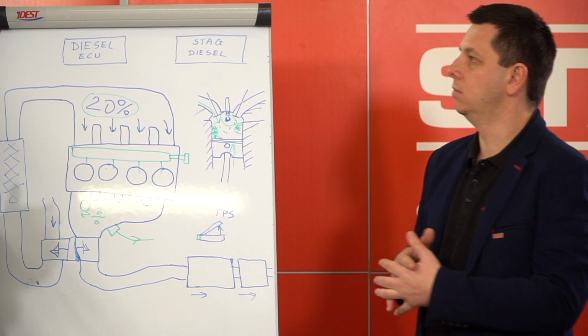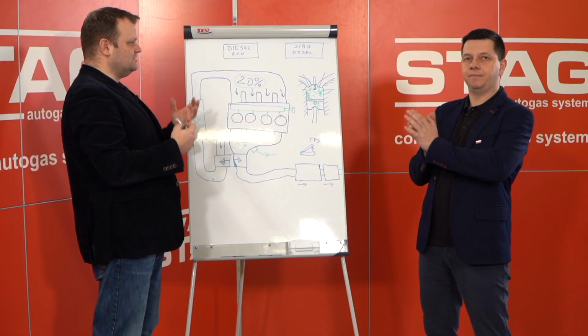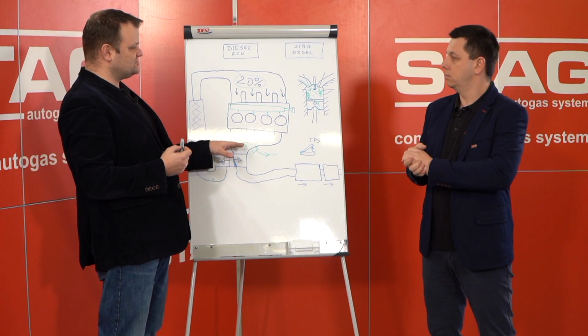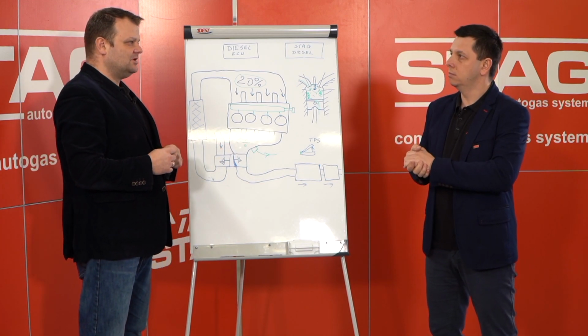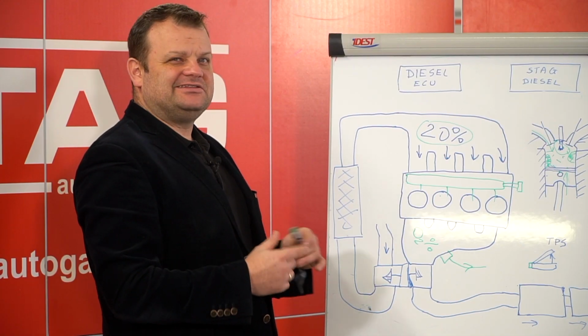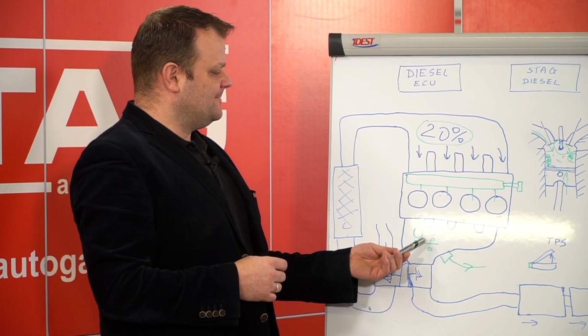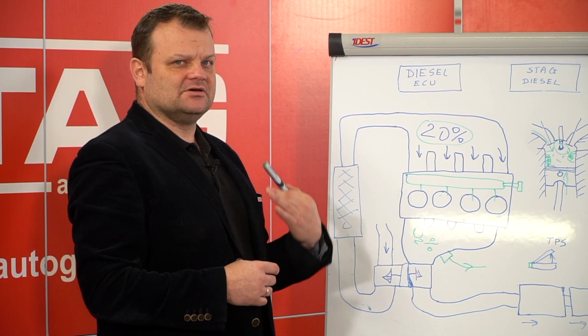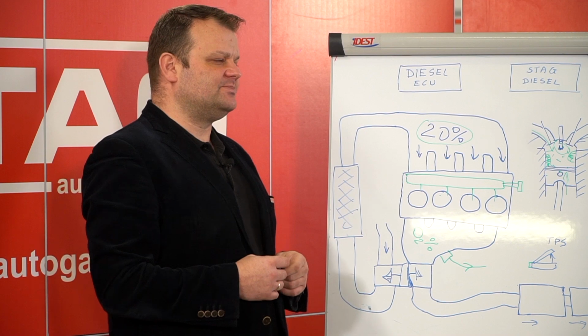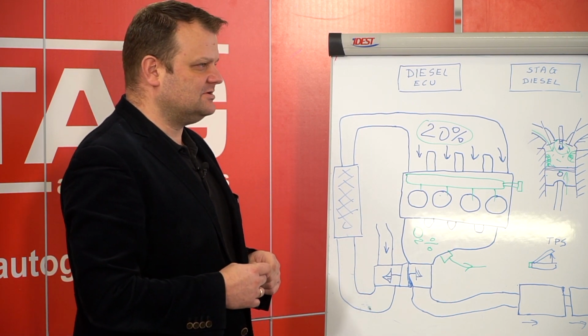Yes, the efficiency of the process in the combustion chamber is out of the limits. That's why the oxygen level should be at a proper dosage. Usually it is a minimum of 3%, but more detailed information will be in our next presentation at a more technical stage.